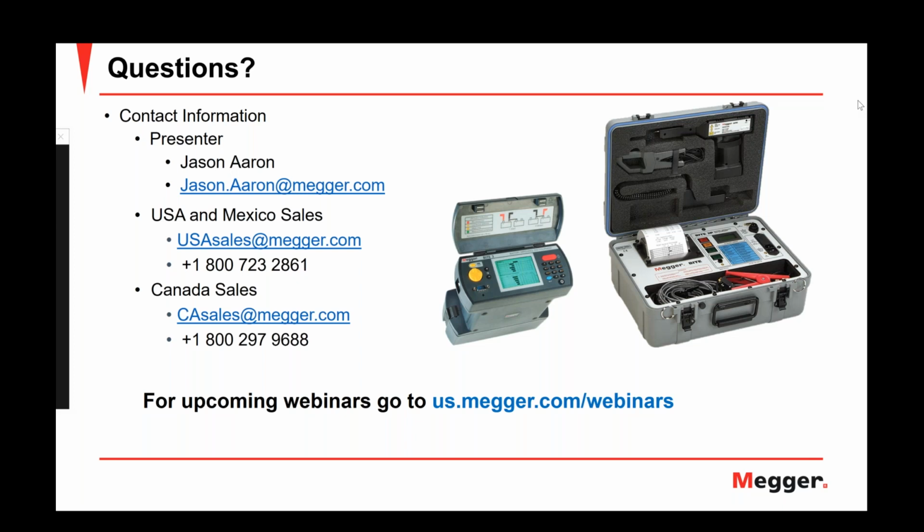The IEEE for the vented lead acid batteries is the 450, for the valve regulated is 1188, and there's definitely good information there on how you should maintain the batteries.